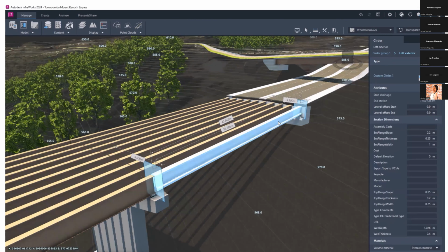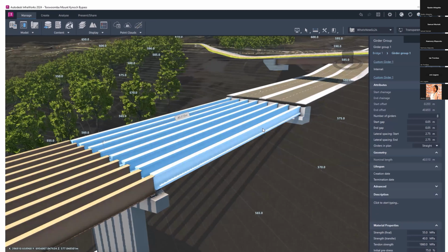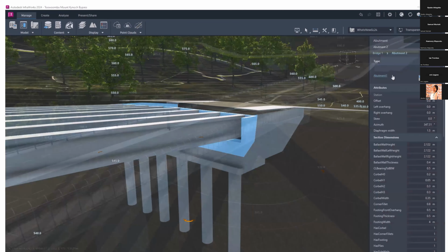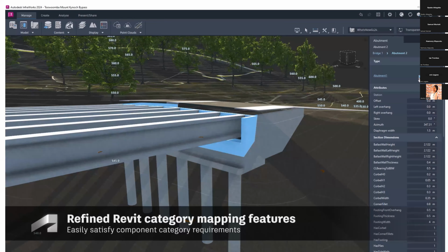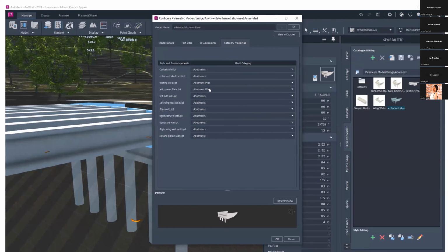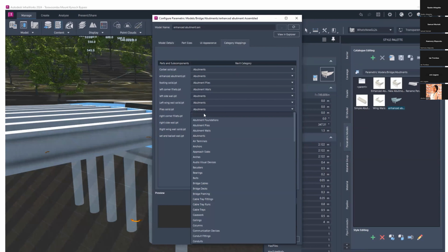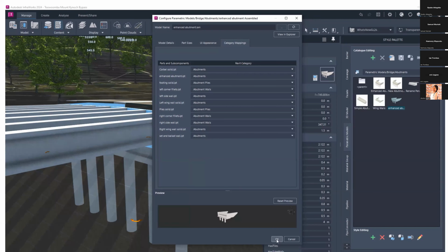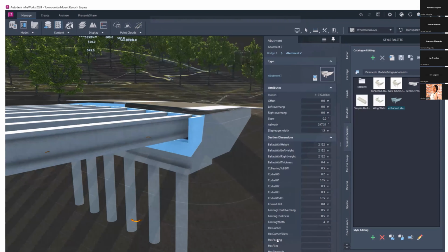The process remains the same once it's imported, it's brought in within the InfraWorks model. So it means that right now I can create this. Initially, we needed to bring in Inventor to be able to complete that with parametric modeling of customization, but right now you don't need to do that. Then there's the category mapping, where I need to choose whether it's abutment, a girder, a pier, so that I'll be able to have specific groups of related objects within one specific.